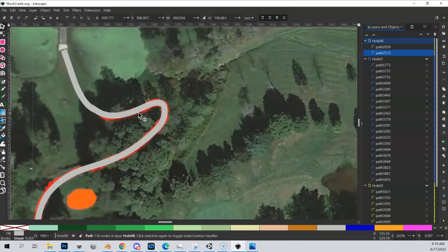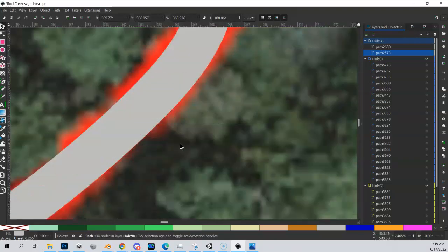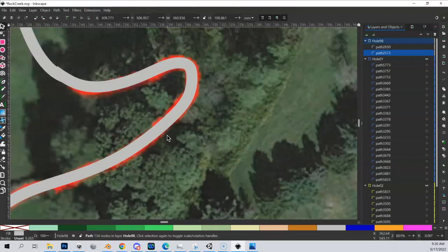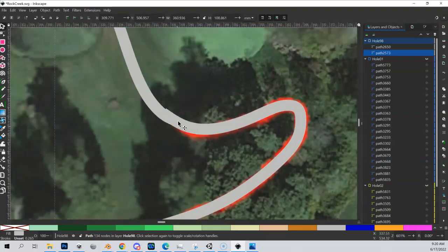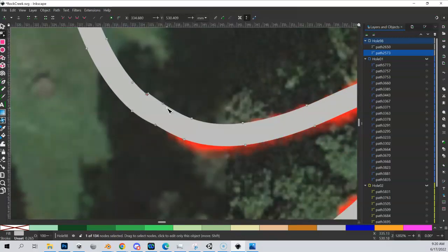And I can see one here. I always go to where I connected that stuff at. Back up here. So you can see here, that does not look right. So I'm going to come in here, and I'm definitely going to have some double node issues. So let me zoom in a little closer and highlight one of these. And you know what I'm doing? I'm just going to delete that guy. Now it looks like there might be one or two left in. Yeah, definitely was a double node there. So this is the stuff you got to be really careful about.